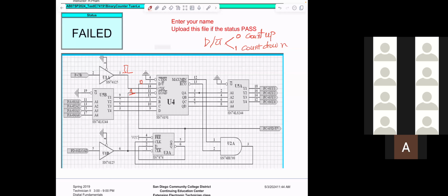However, the output will be brought up to the standard logic. If you want input pin 2 to be the same as the output pin 3, then pin number 1, the enable, must be 0. Okay? If it's not 0, output and input are isolated. They're not the same logic.